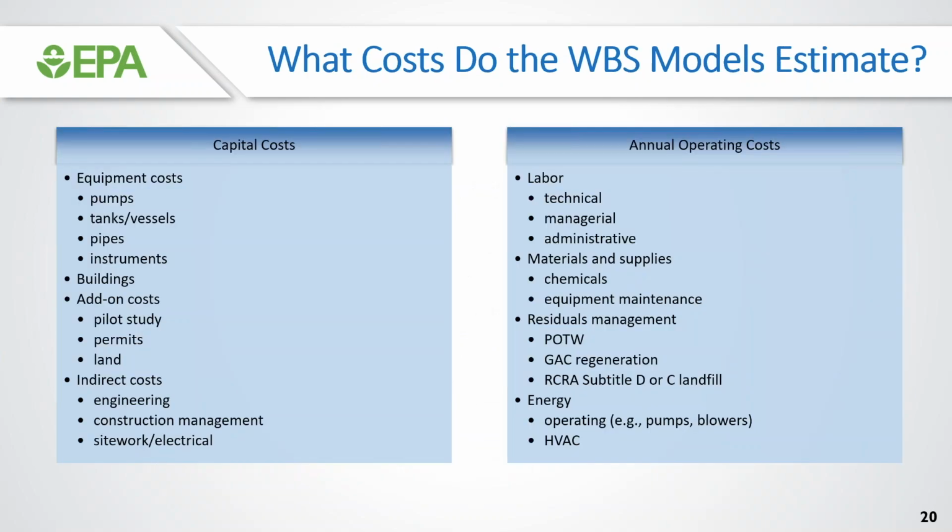And so the costs are actually broken down into capital costs, which are going to be your investment cost, the cost of pumps and so forth. And then pilot studies and permitting would be included in that, because that would be more of a one-time cost. But then it's also tracking the annualized costs, so cost of labor, cost of chemicals, cost of maintenance and pump replacement and so forth, and even down to how much energy it might cost to run a pump.